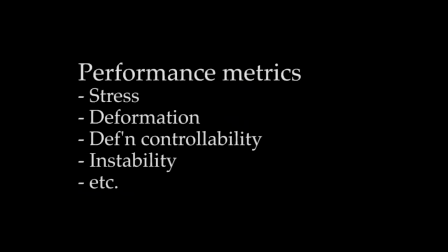Now that we've gone through each of the 4 grasp evaluations, you'll notice how we measure different quantities at the end of each. These quantities are what we call performance metrics, and these are what practitioners care about after applying a certain grasp. For example, we measured the stress of the object after pickup, because practitioners may care about seeing whether a grasp will induce stresses that are past the breaking point of the material, and if so, they should probably want to avoid using that grasp in the real world.